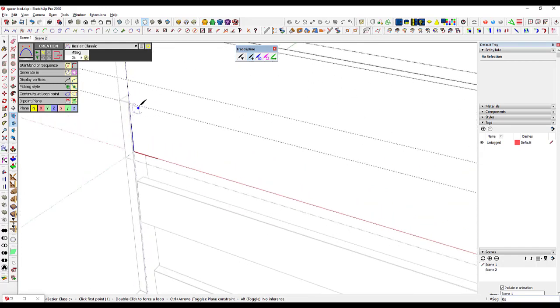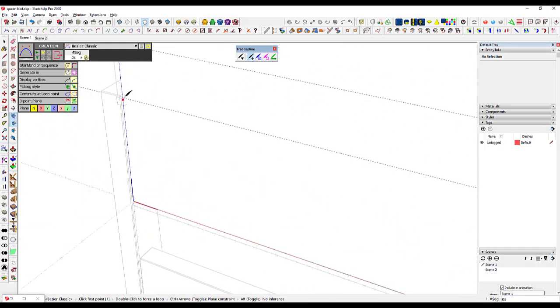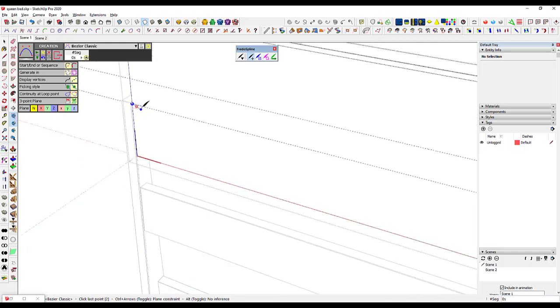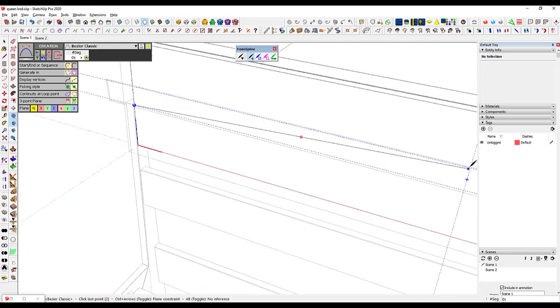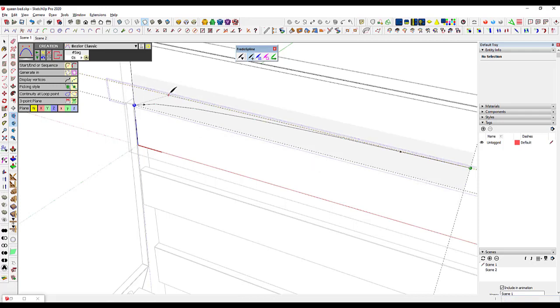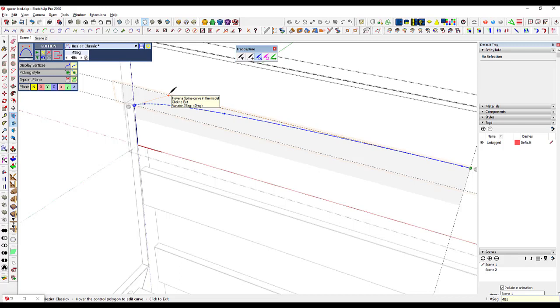to draw on, but I'm going to start with a point there and here, and I'm just going to drag a point out here someplace and put it on that guideline. And there aren't very many segments there, so it's kind of a rough curve. So I'm going to increase the smoothness of that. Let's say 48. I'll just type 48S. This is the same as in the old version.